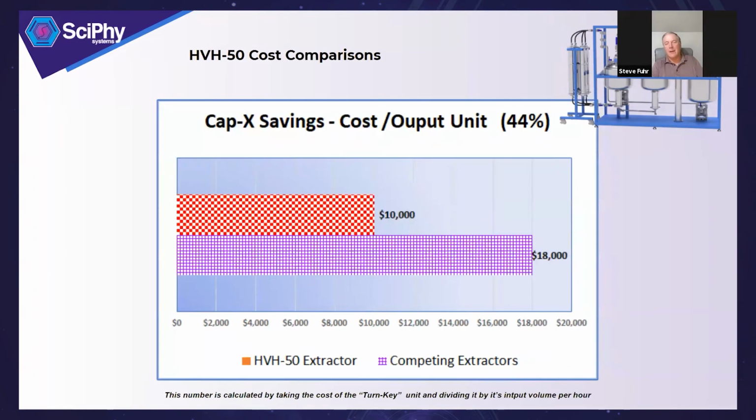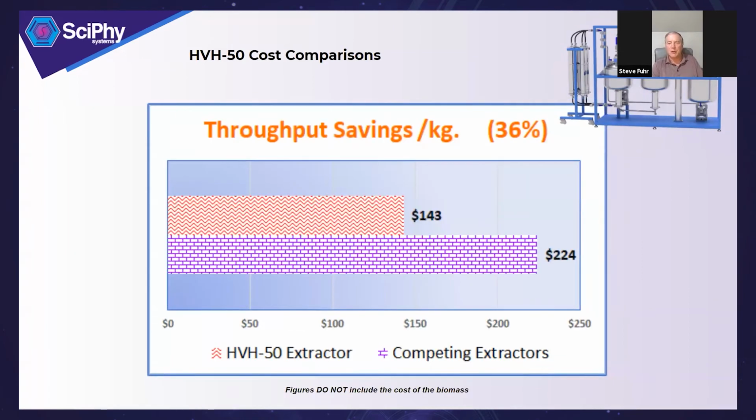So, Emmett, if I could just add one thing to throughput real quick, and that is to make sure you're assessing your bottlenecks. We find people undersize their solvent recovery quite a bit. One of the more classic areas that people undersize is their distillation capacity, where they're producing, say, 10 liters of crude an hour, but their distillation rig does 0.6 liters in an hour. And so it's important to assess those bottlenecks so that you're not choking your throughput capacity.